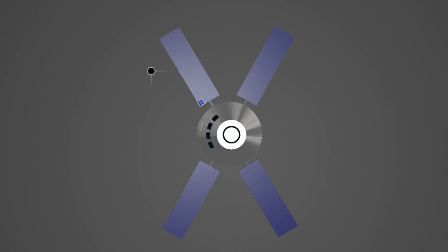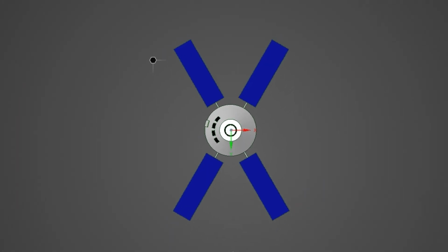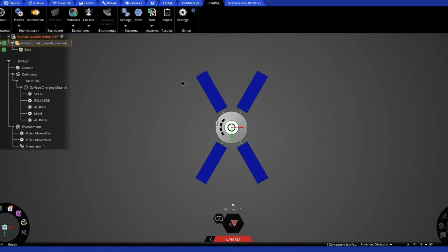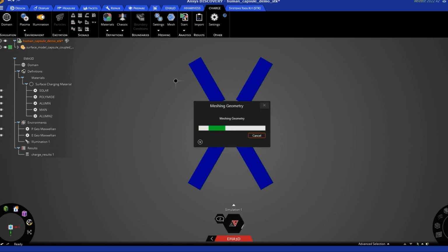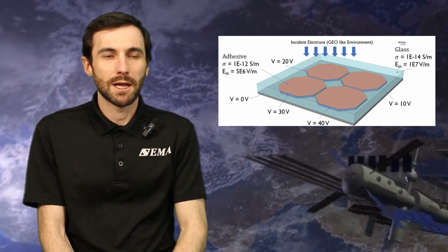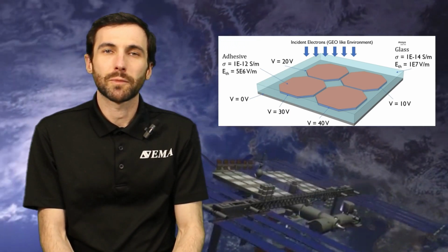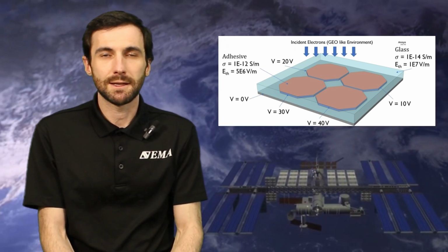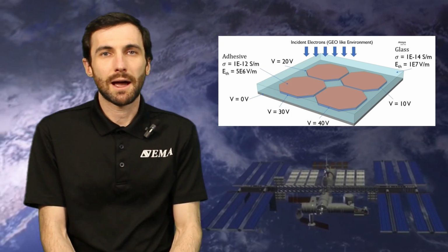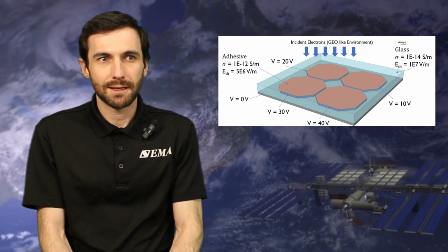In Ansys Charge Plus, we have the ability to model how that radiation interacts with the bulk matter and the materials and the components and solve for the fields in 3D. It is a very novel technology in its ability to connect full wave electromagnetics with radiation transport. One of the things we really want to focus on is modeling these high energy electrons and their proper energy, typically in the MeV region, and how they deposit inside the solar cell.